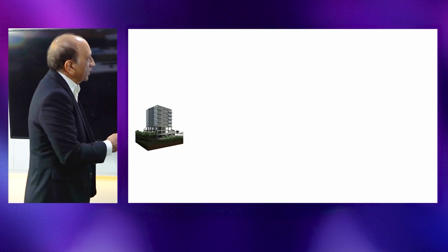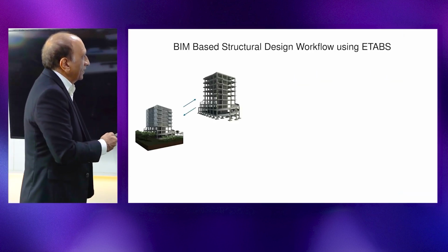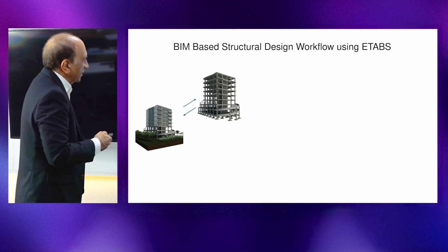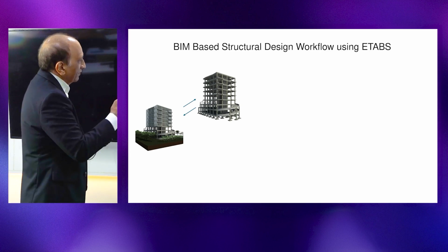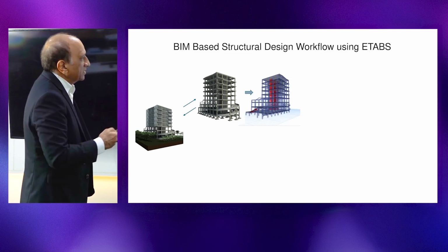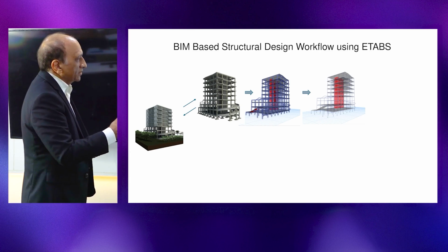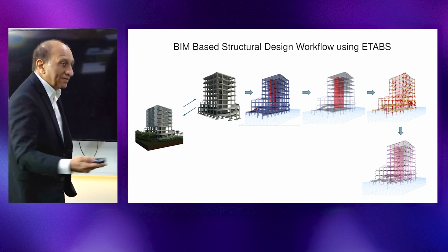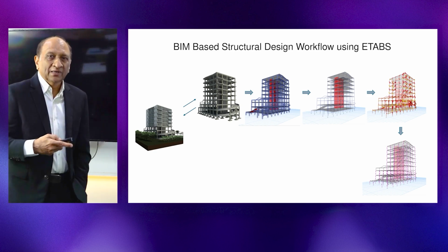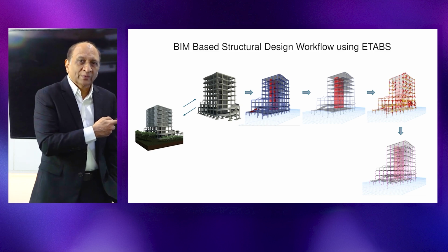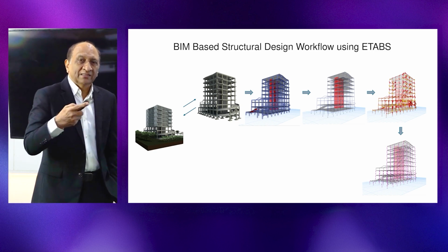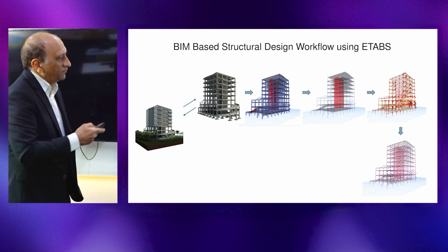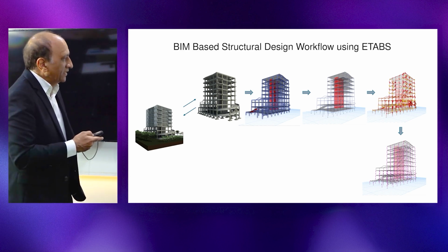So this is the workflow using the traditional way. From the building, for example, we can get the structure model, we get the analysis model, we get the analysis results, we get the D/C ratios or reinforcement from there, and then in the detailer, Tekla can generate all the rebar, the reinforcement details and the cage, and we get the full rebar model generated in 3D from the information from the design, and that is part of the detailer.